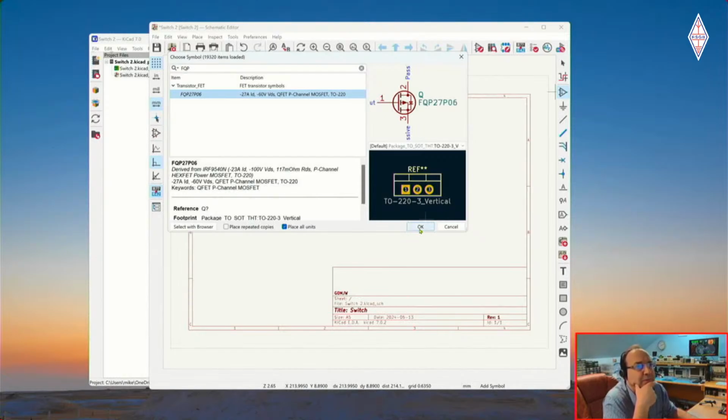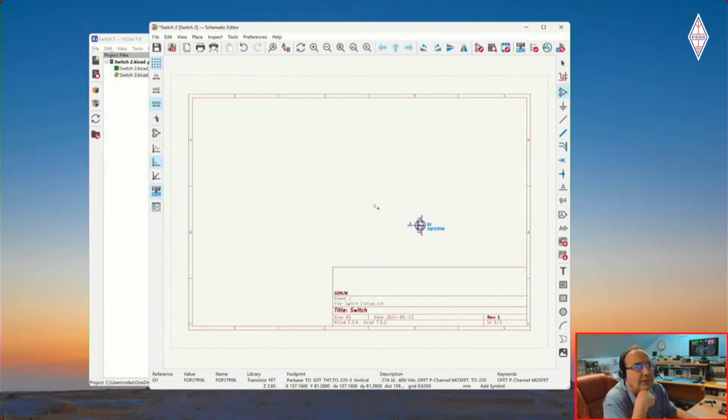So again, you can design the symbol and you can design the footprint. The footprint is what it looks like on the PCB, and generally there are different layers, which I'll come into when we do the PCB design. I'll explain what the different layers are, because there's copper, but there's also labels and what we call the silk screen, which is the thing that gives you all the component legends and what have you. So let me take that and I'll just place it roughly there.